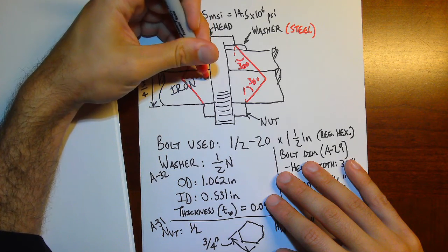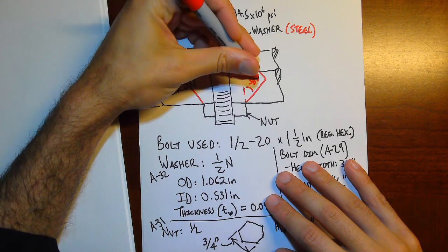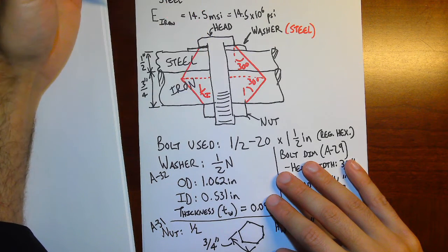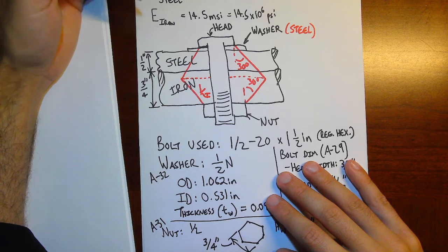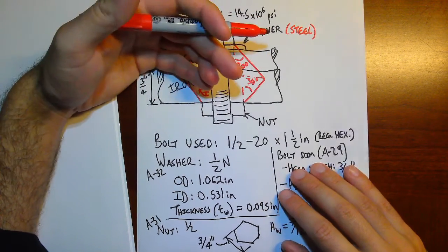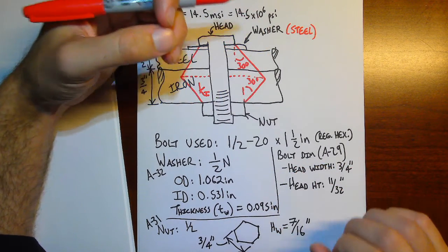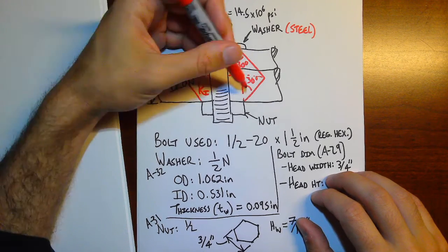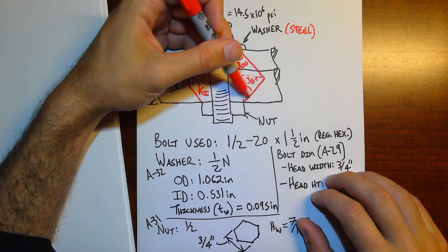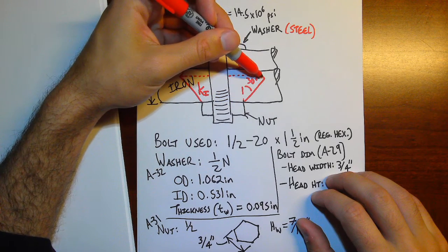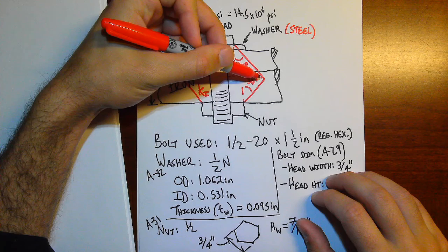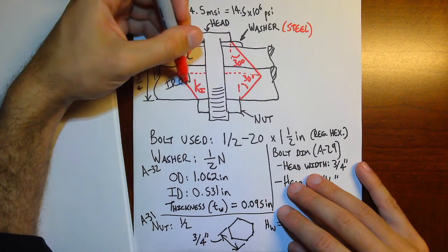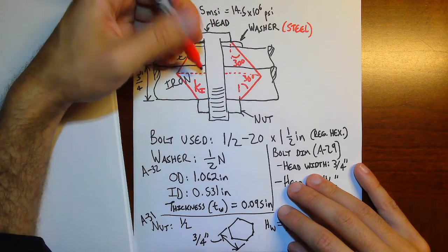So if the point is indeed where I think it's going to be, somewhere in the iron, then I can think of this bottom half as one frustum, so it's going to have its own stiffness. Based on the way that we derived the expression for stiffness, I can compute the stiffness of a cone going out as soon as it makes a turn, like around this point, or changes material. I have to do a new computation, so I can compute the stiffness of this bottom part.